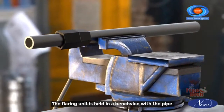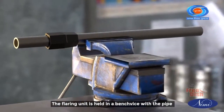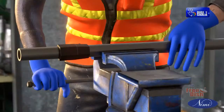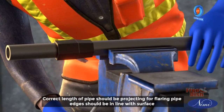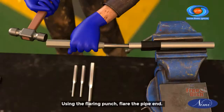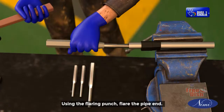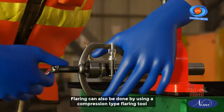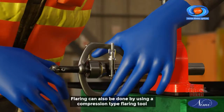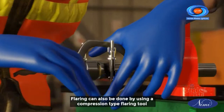The flaring unit is held in a bench vise with the pipe. Correct length of pipe should be projecting for flaring; pipe edges should be in line with the surface. Using the flaring punch, flare the pipe end. Flaring can also be done by using a compression type flaring tool.